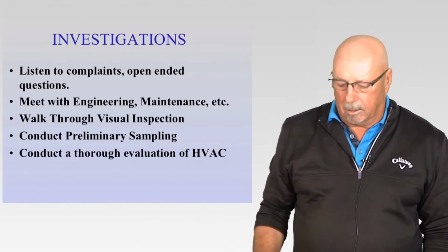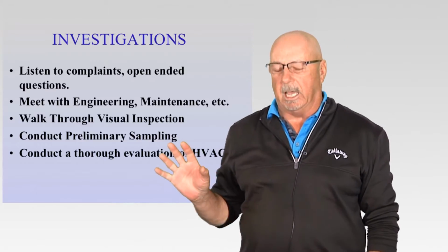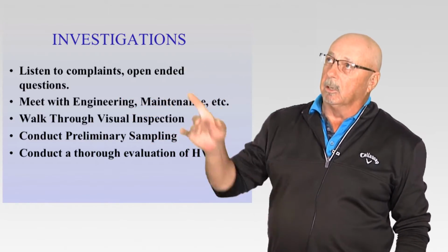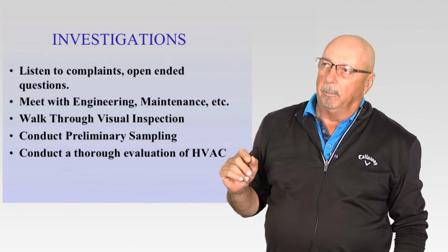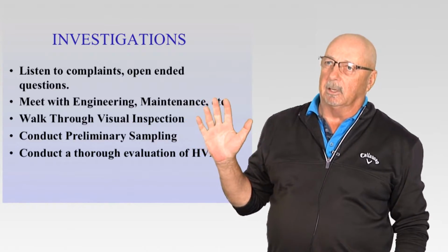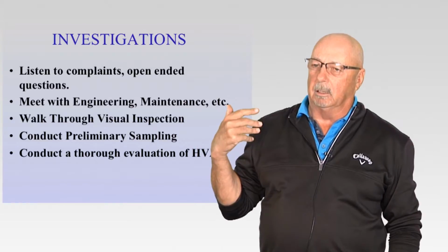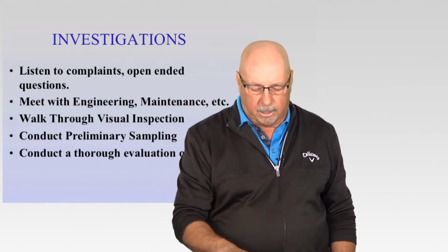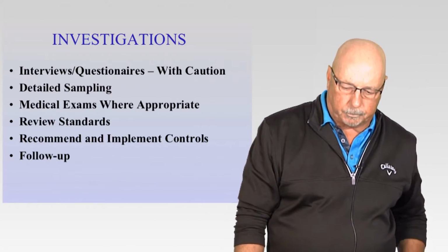But we want to conduct a thorough evaluation of the HVAC system, not only the mechanical system, but also above the ceilings. Many times I've gone above ceilings and I see supply ducts that have just been disconnected. And so you think you're bringing air into the space and you're not.